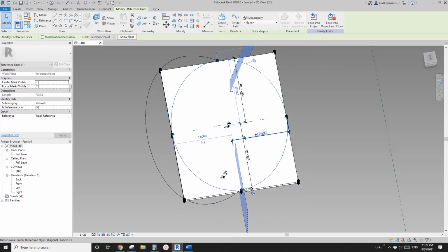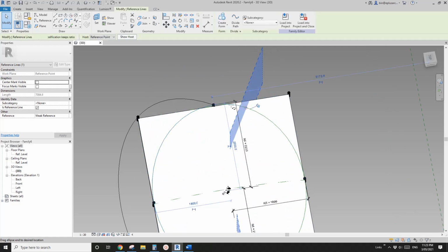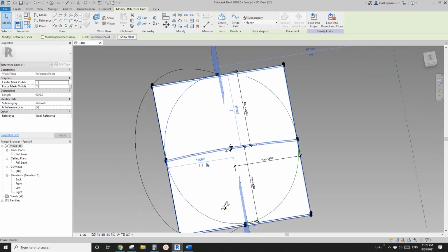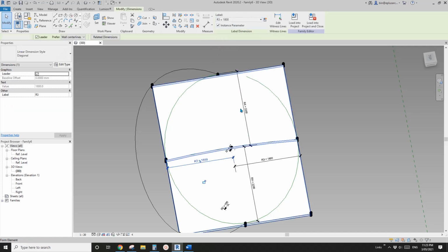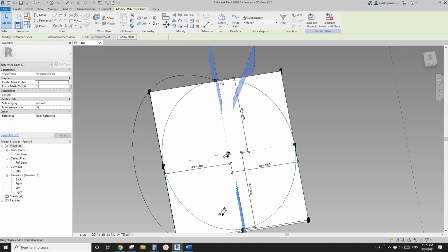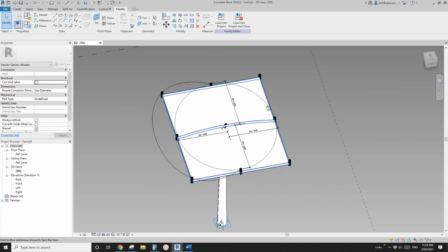And then I'll just tab, select this one, and drag this back to here. And this part, same, tab, select, drag this to this point, and see, looks like we can add some dimension here. I'll just try add A3. Good. Sometimes it will say over constraint or something like that, but yeah, I think it's all good.